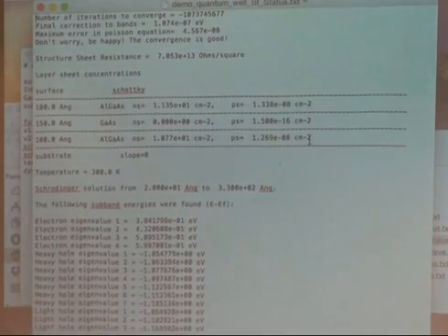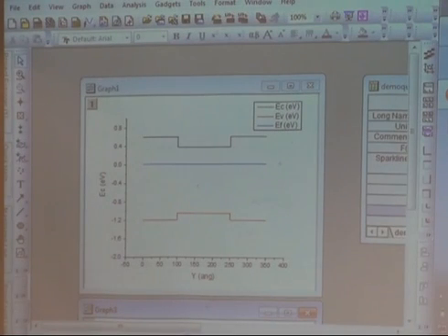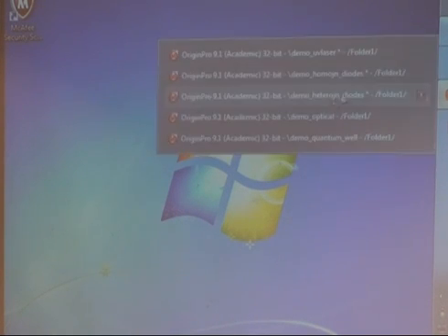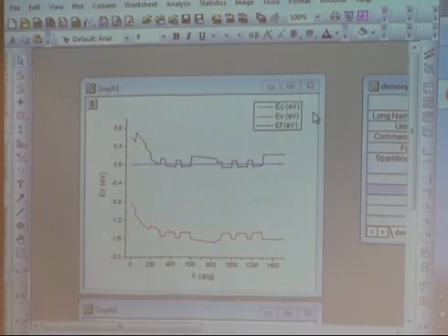And then, the more interesting structures you can design, you can put this in and calculate your band diagram and all that. Let me show you a couple. For example, if you're designing some sort of an optical waveguide, here's a design. It's an interesting design which has many regions, some for light confinement, some for electron confinement. So for example, you want light to be confined here, but the electrons to be confined there. That's a design that's heavily used.